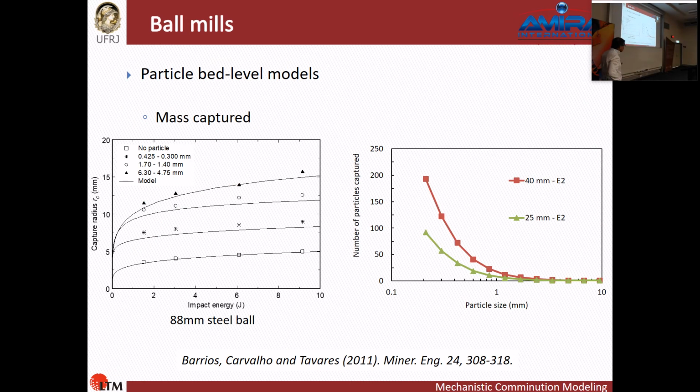But now, how can we couple the two pieces of the puzzle together? As I mentioned, you have to describe what's going on at the bed level, to be able to answer how much material, what Malcolm calls sub-DEM material, which is not in the DEM simulation, but you have to account for it in breakage. How many particles, or how much material, is nipped in each stressing event?